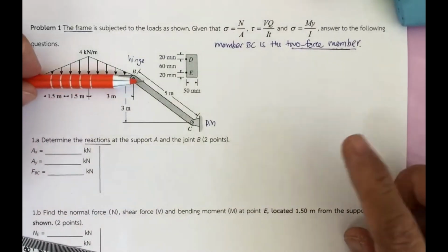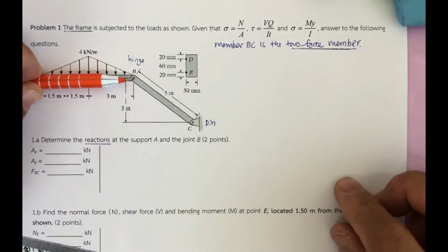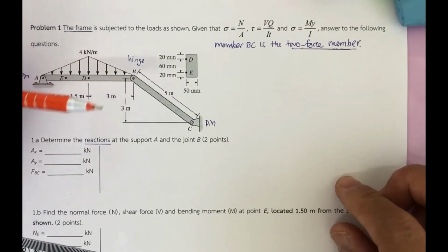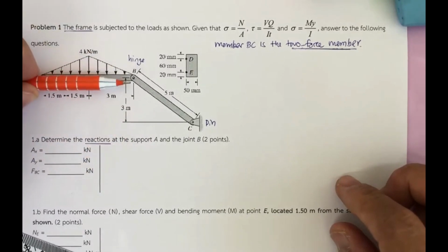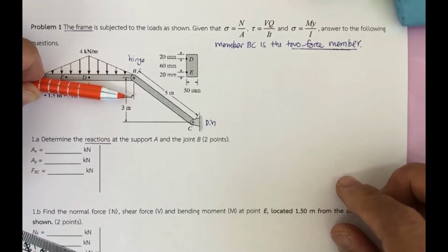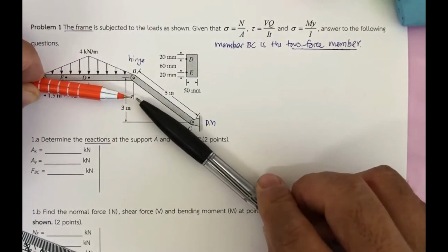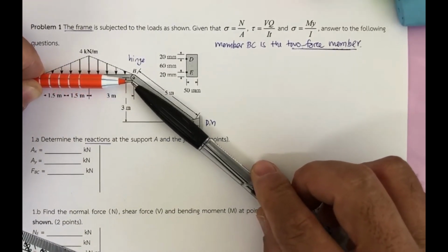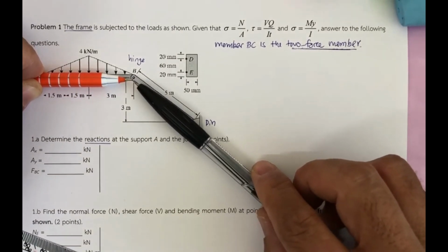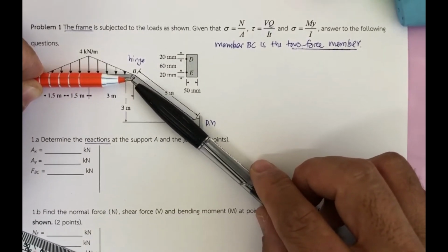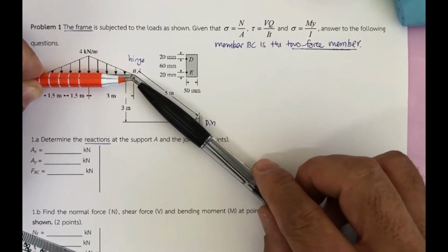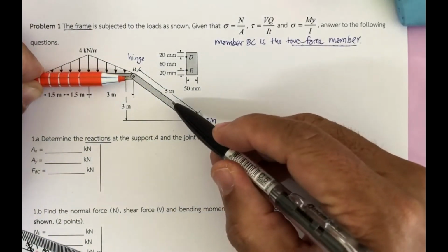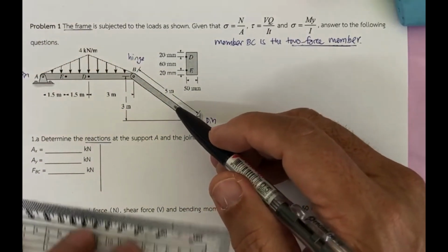Also, if you consider how the structure reacts under the force, you can see that under the force, the beam ADB is going to rotate, something like this. That means member BC is going to react to balance it. The force at point B acting on the beam is going to be in this upward direction. That means member BC is going to be in what's so-called compression.